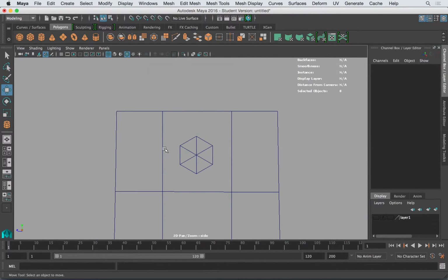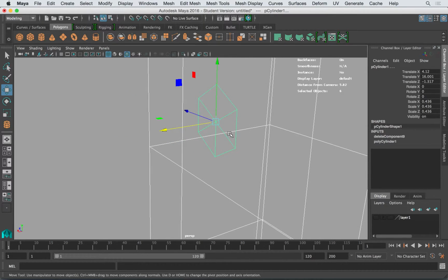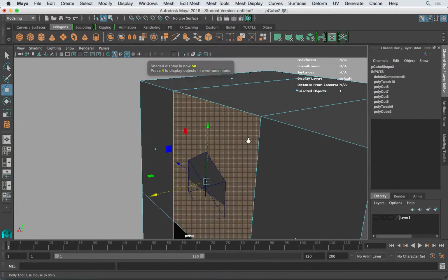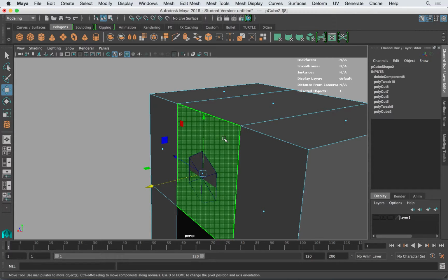So to open a hole here, we need a bunch of other faces. I could select this face and just extrude it so I can get closer to that. So I'll do some offsetting. I'm going to extrude that.